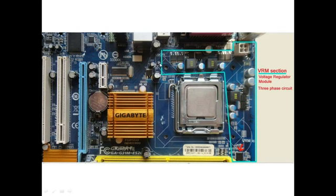And this section which is near to the CPU, we call it as a VRM section. VRM stands for voltage regulator module. The purpose of this section is to give out supply to the processor. This is a 12 volt connector, PS connector. The VRM section takes the 12 volts as the input and gives out a supply to the processor, which we call the CPU core voltage.